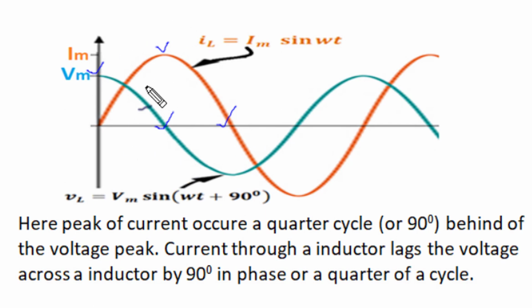When sine and cosine alterations have a 90 degree phase difference, or a quarter cycle phase difference, when one of voltage or current is at peak value, the other is at zero value, or when one is increasing in one direction, the other is decreasing in its previous direction, and vice versa. As is clear from this wave shape, when current has zero instantaneous value, voltage is at either positive peak or negative peak, or similarly, when current is at positive peak or negative peak, voltage has instantaneous value 0.